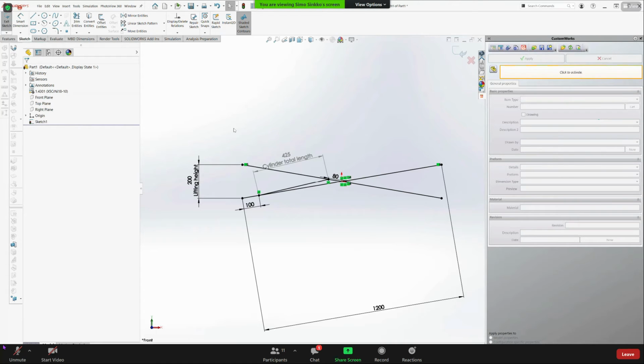Well, we have forces in y direction from the load. Then we have reaction forces at legs, and they have also some kind of y component and x component. X components should be eliminated by each other. And then the y component of the load should be equal to the sum of the reaction forces at legs and the y component of the cylinder. I guess that's it.